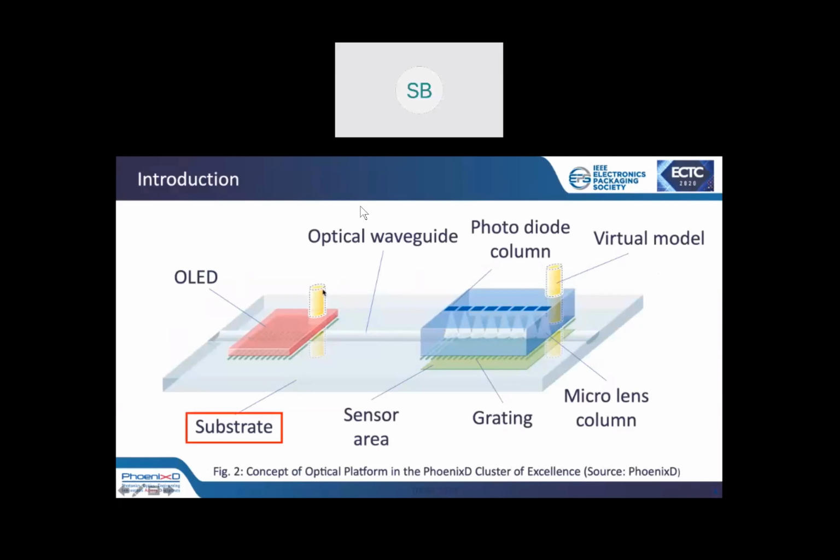Regarding the optical attenuation, on a very small substrate, like a 4-inch substrate, the optical attenuation depends only on the roughness of the surface. The attenuation due to the reflectance of the gold can be neglected in this case. Therefore, only the roughness and the surface quality are the goal to reach.